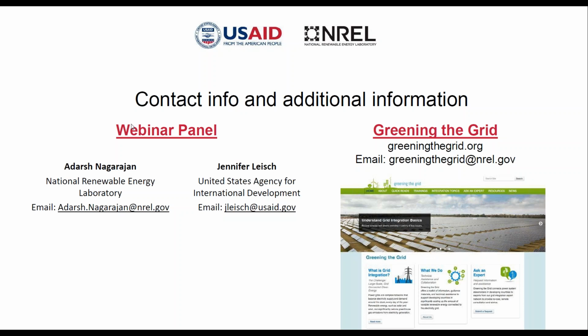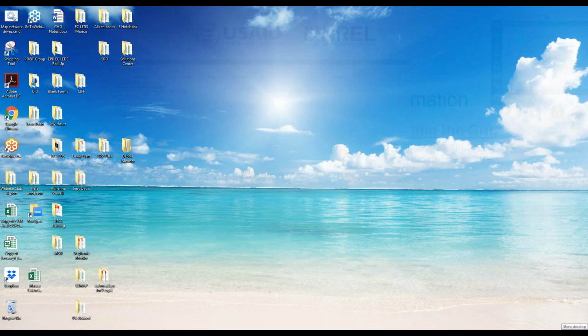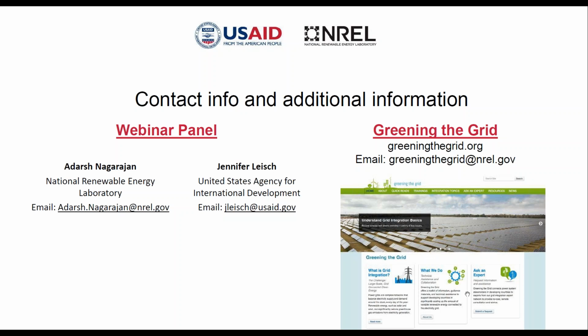Islanding is certainly an issue that has come up in terms of providing additional resilience to facilities and the grid. Are there certain ways that islanding is being addressed in some of these grid codes? How are DERs being asked to respond in this situation? That's where the grid code specific to fault ride-through comes into the picture.